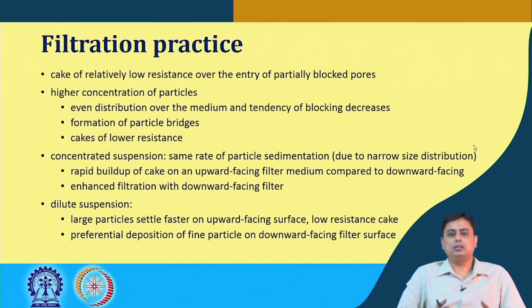These particles of high concentration distribute evenly over the filter media, and the tendency of blocking the pores goes down. That results in cakes of lower resistance.